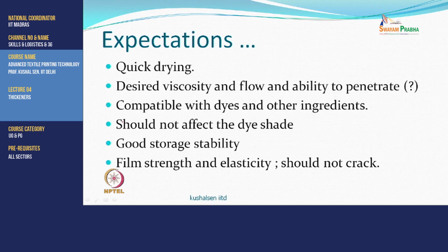And if it so happens that the whole film goes down, breaks, the dye also comes out with it. So, there should be elasticity in the film, in the sense that at the temperatures when we are working, it should remain flexible enough so it does not fall off.